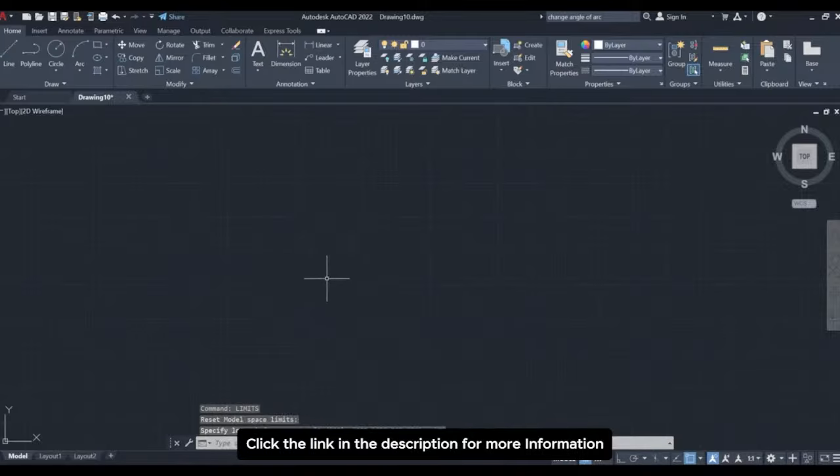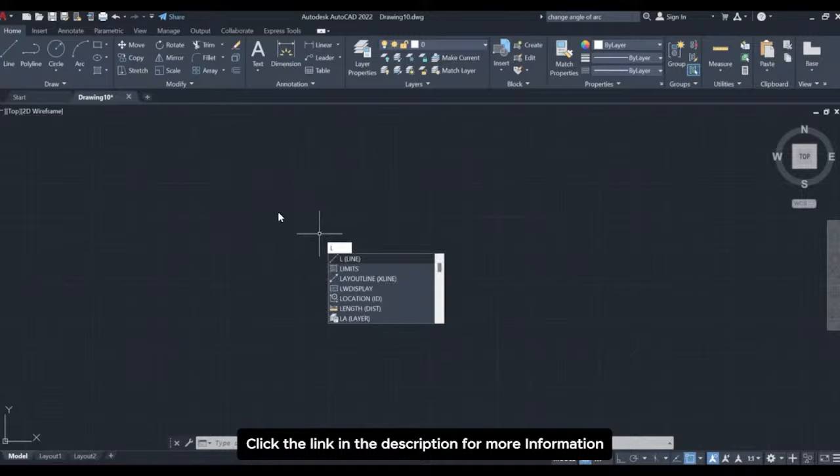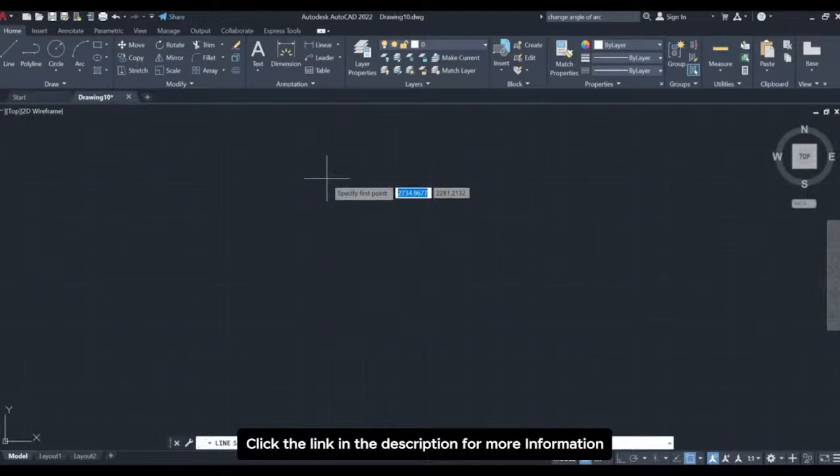All right. Now that we don't have any limits restricting us, let's get started with lines. In order to use any command, just type the letter directly. You don't really have to click anywhere in the command or anything like that. Just type the letter L while you are in the workspace. When I hit L, this drop down option comes in. I hit enter, and that's the command for line. It asks me to specify my first point.